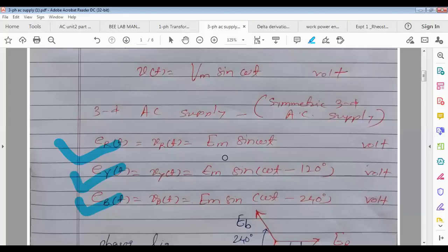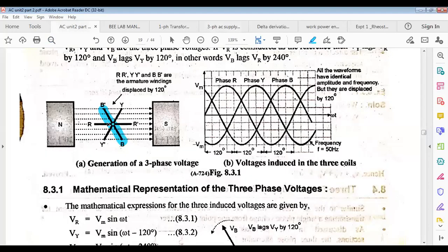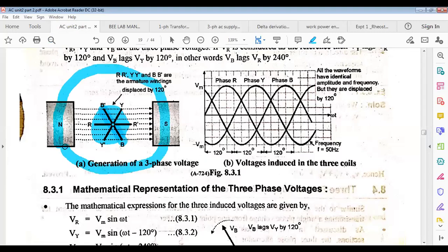In India, electricity is generated using a generator, and that generator is 3-phase AC. Like this, the 3-phase windings are put on the rotor and stationary stator poles are there. Okay. So this is the arrangement, and whatever the 3-phase induced EMF in these 3 windings, that is Vm sin of omega t, Vm sin of omega t minus 120 degree, minus 240 degree, that is the output, electrical. Input is mechanical. Okay. This is the case for smaller size generator.